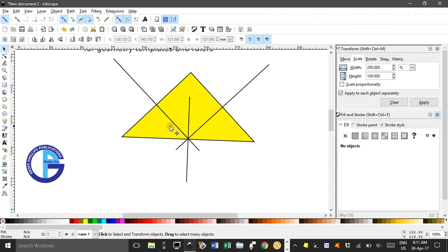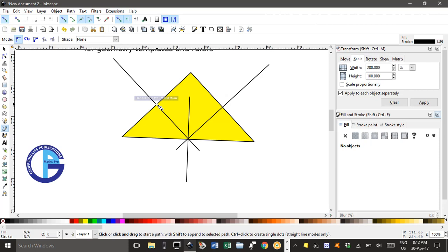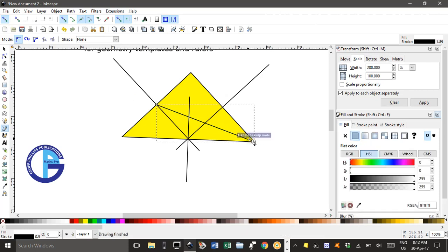Now I don't want this point here, which I think represents the orthocentre, but what I do want is the midpoint only joined to this vertex, but I should be able to do that just using the bezier pen tool. If I click there, yes, on the intersection, and then there, it'll snap to the cusp node and enter.